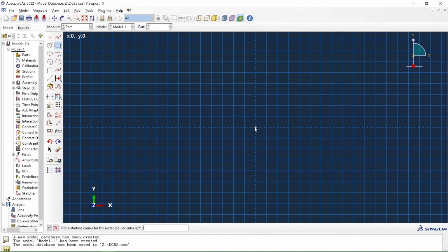But let's start. What you'll find out when you go through the configuration that we've been given is that the cantilever length is about 5 mm shorter than the first part. So the total length of the cantilever is 285. I'm first going to create a base cantilever that's 0.285, 0.0127. So that's my base cantilever.